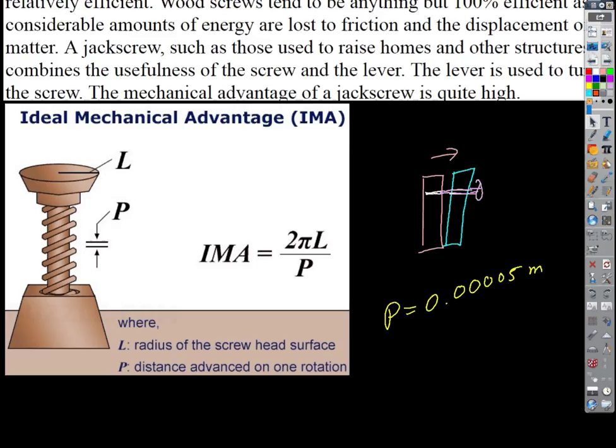But if we want to actually pull something together, you see what the problem would be. If you look at the cross-section of a screw, what's it look like? There's the core, and then it's gonna look like that, sort of triangular cross-sections, right? If you make them too fine, what's the problem with that? It's just a cylinder. They're gonna break off, right? When we apply a shear force to those, they're just gonna break off at the base. So we want something husky enough that it's able to withstand some force. Now, you do get the benefit of the finer the thread count, the more of those you get too, right? Okay.